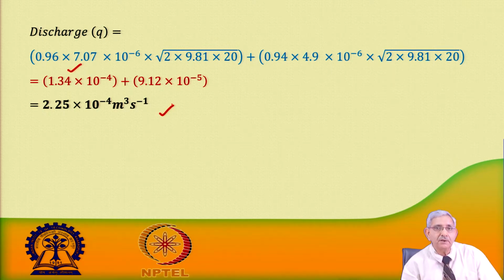So, if there are similar sprinklers attached, say 10 numbers, 15 numbers, 25 numbers, we will get the total discharge. Now, this total discharge from all the sprinklers will be used to find out the discharge from a lateral, or if there are so many laterals, so much of the discharge which is required, then we will use this value to find out the system capacity.